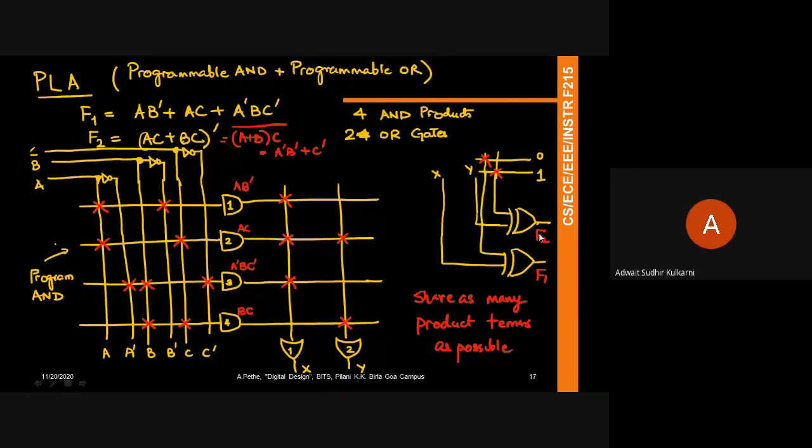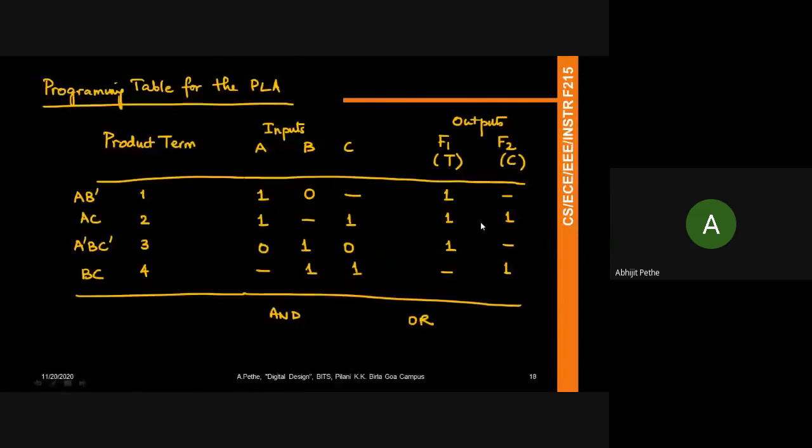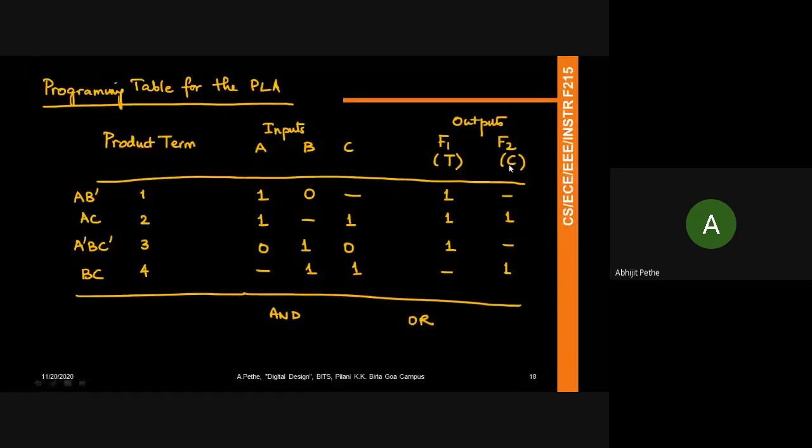And one more doubt. Why aren't we including the XOR gates in that NKM PLA count? Because that's normally optional. Not all PLAs have it. So whenever we talk about the PLA programming table, we worry only about the AND and OR gates. And this information is got when you give this input. When you give a true and complement, that encodes the information as to how the XOR gate needs to be programmed. All right. Thank you.